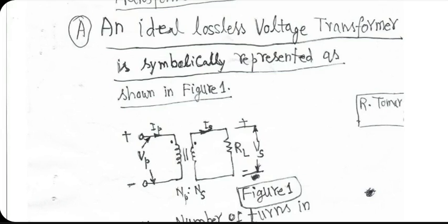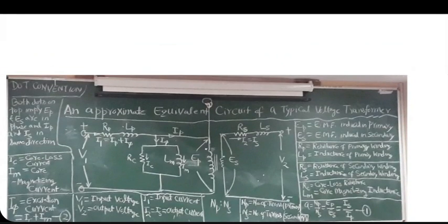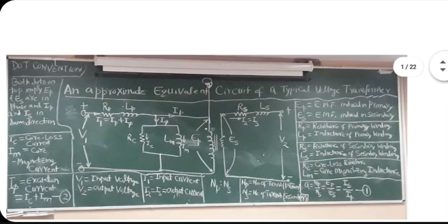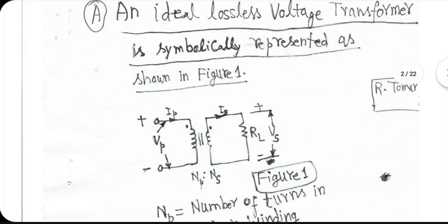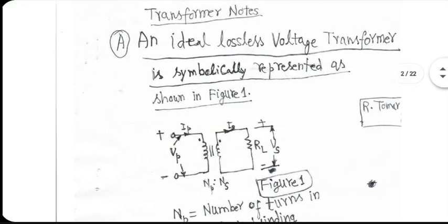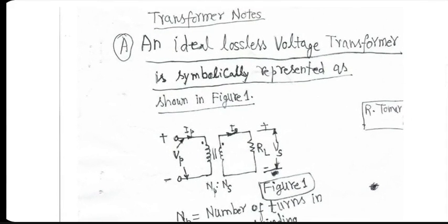There are losses like hysteresis loss, eddy current loss that make what we call core loss or magnetic loss. Okay. And all that has been captured reasonably accurately in this equivalent circuit, which is a much better and much more accurate description than what is shown in figure 1. But figure 1 helps you in understanding the concepts quickly without having to worry about losses.